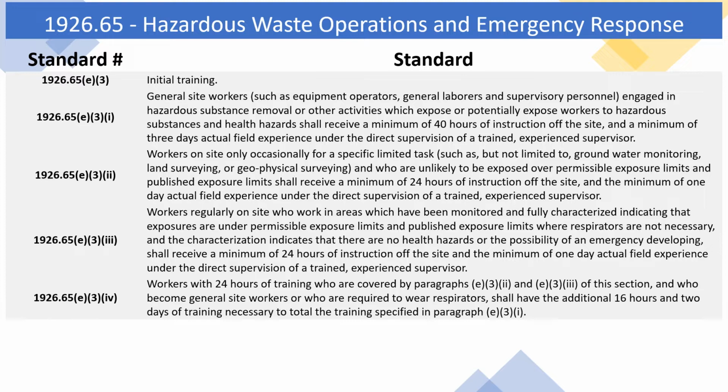1926.65 E3(3) Workers regularly on site who work in areas which have been monitored and fully characterized, indicating that exposures are under permissible exposure limits and published exposure limits where respirators are not necessary, and the characterization indicates that there are no health hazards, or the possibility of an emergency developing, shall receive a minimum of 24 hours of instruction off the site and a minimum of 1 day actual field experience under the direct supervision of a trained, experienced supervisor.